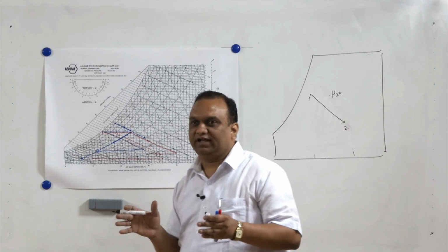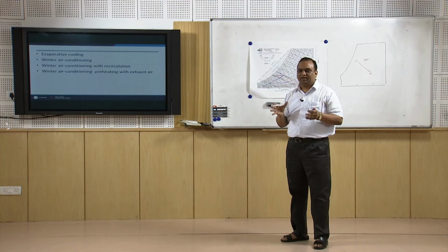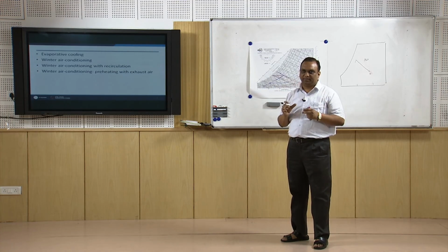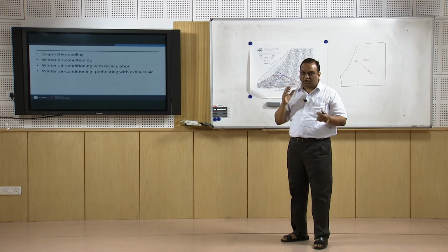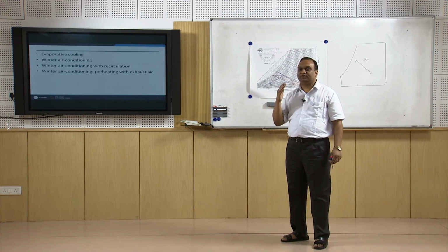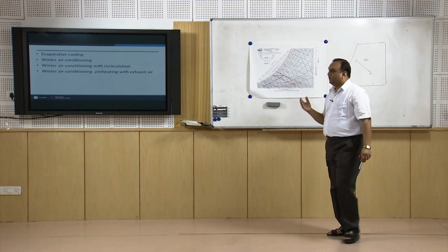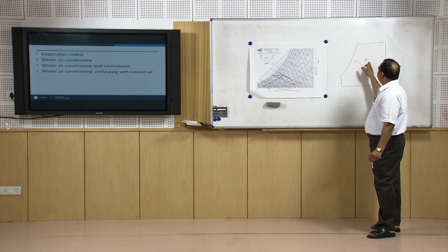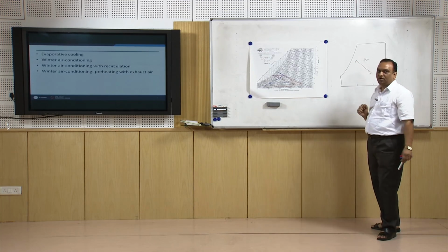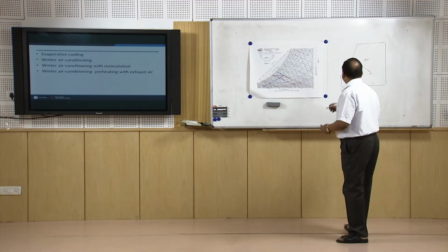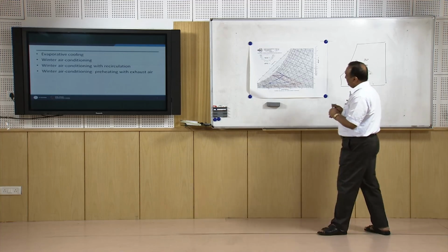So, if you put silica gel in moist air, the silica gel will absorb the water, and in this process the latent heat of condensation is liberated, and due to this latent heat of condensation, the heating of the air takes place and the temperature of air rises.